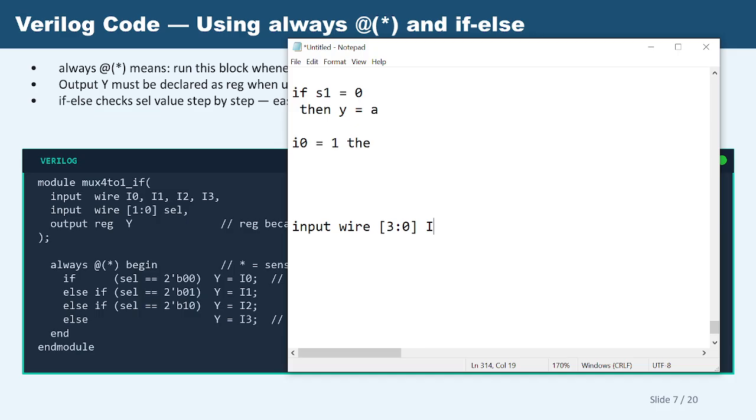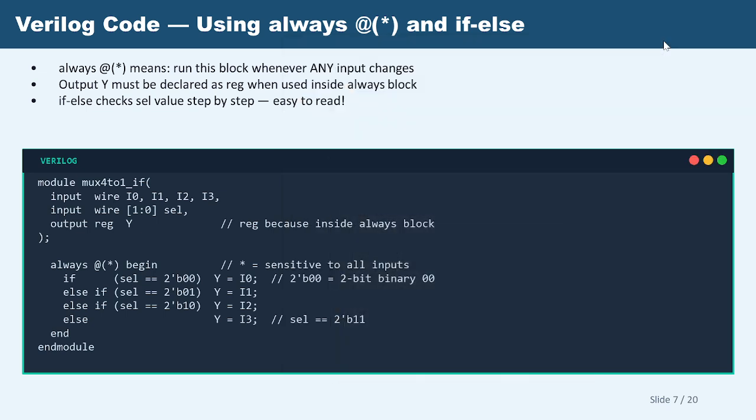So what you are mentioning defines the bit width of the select lines, how many bits of input you have and how many bits of select lines there are. This is the form of writing, so rather than writing select 1, select 2, or I0, I1, I2, I3, you can keep it short like that. Now look here, in the previous class I was not mentioning wire and reg in the design code, right? We were only mentioning that in the test bench code. So how come we are now using wire and reg here in the design code? Did anyone get a doubt on this?